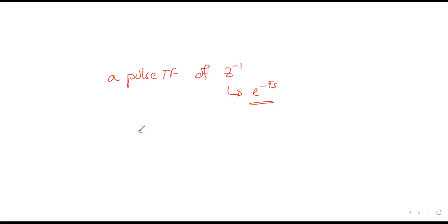So in a block, Z inverse can be given in this way. If you have x(k), which is a sequence, or X(z), then x(k) becomes x(k minus 1) divided by 1 unit, and your X(z) will be Z inverse X(z). Okay. So this is how we represent Z inverse using a delay in the pulse transfer function.